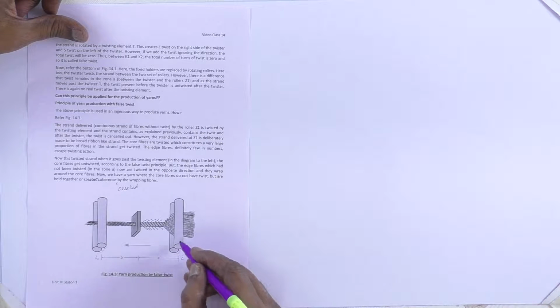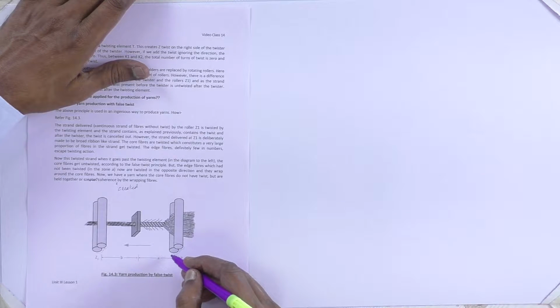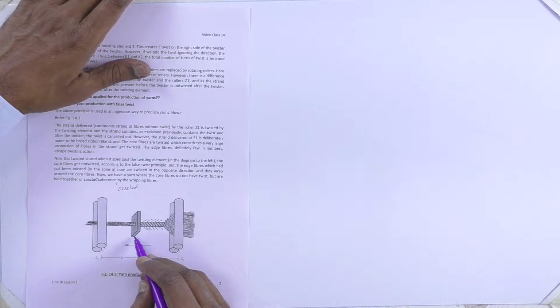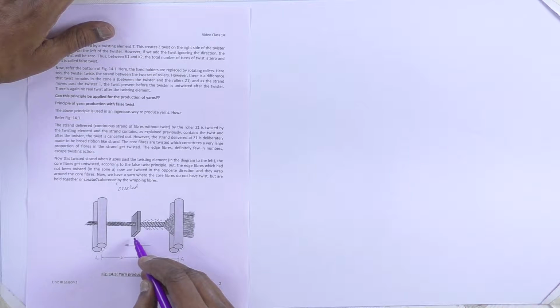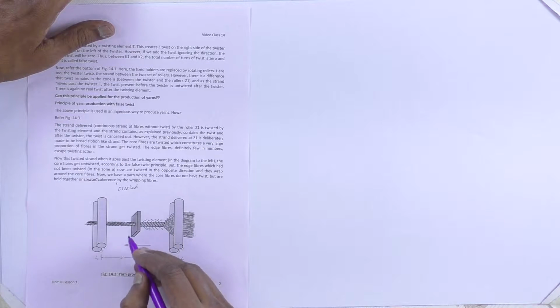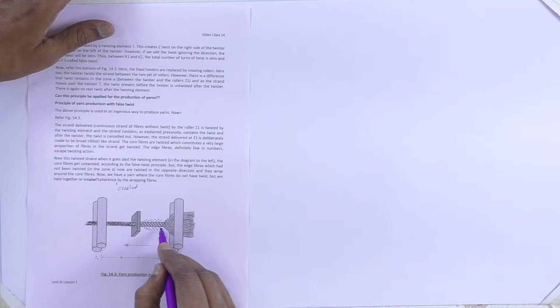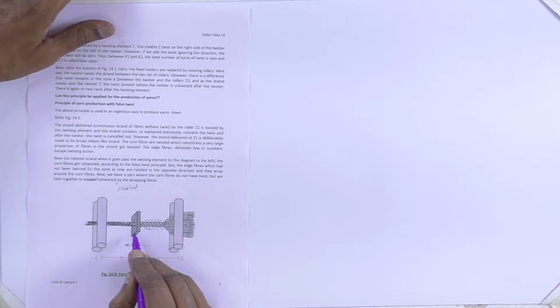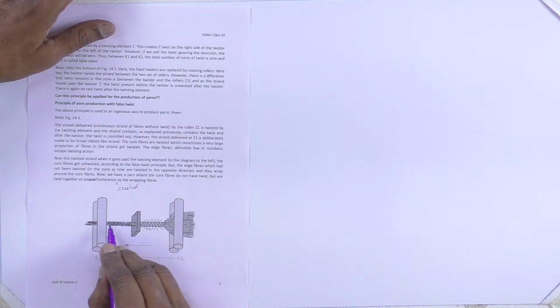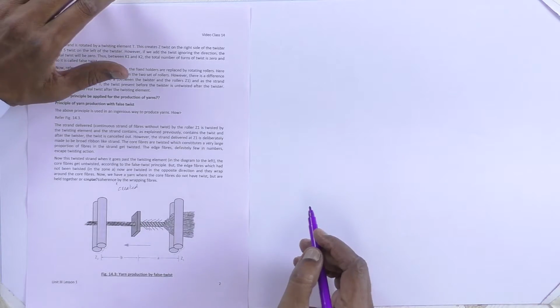You can again see here a set of rollers. We can call it the drafting roller, the front rollers of the drafting system. The drafted material comes here, and this is a twisting element or false twisting element because it is rotating between these two sets of rollers, and by its rotation it creates a false twist in this area. After passing through the twist imparting element, the material that has been twisted becomes parallel. This is what we have seen in the previous diagram.